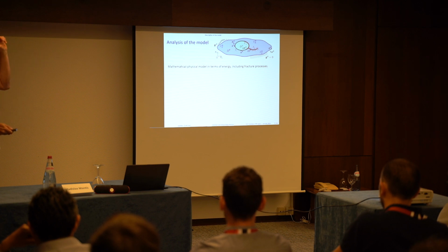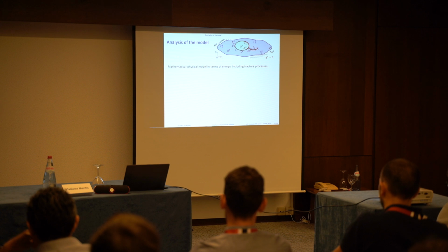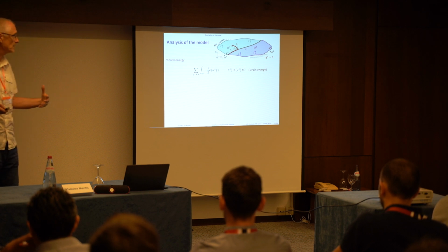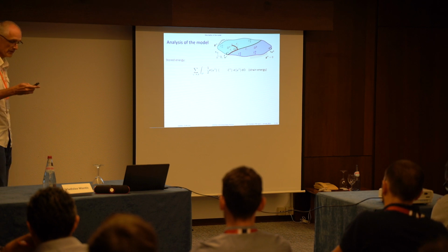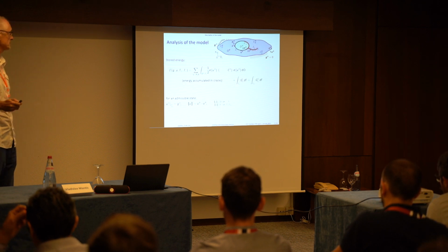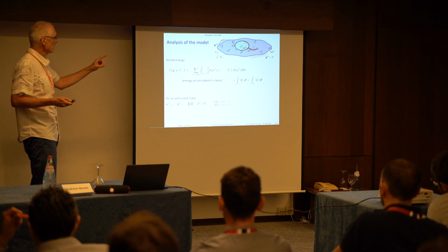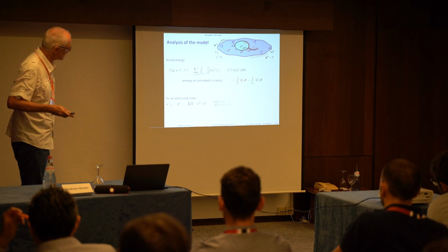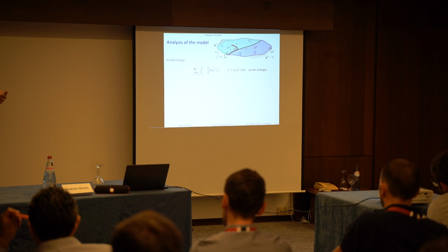So as I said before, I want to explain the model which is based on variational formulation. So it can be described in terms of the energy. The standard variational model of Francfort-Marigo considers the energy accumulated in cracks using the standard parameter GC. Well, looking at the interfaces, this is the last term within the theory of adhesive contact. In fact, we